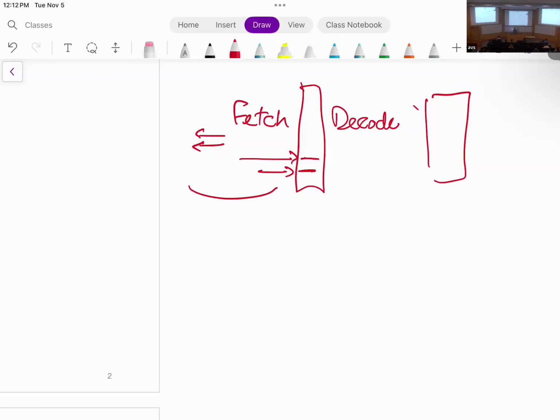There's an additional detail we haven't talked about in this class yet: the fetch usually goes through the instruction cache and brings things in, and that's why you want instruction fetch just moving forward. For the purpose of your homework and quizzes, if you need to stall, assume that your fetch can continue, unless we explicitly say that your fetch needs to be stalled as well, okay?